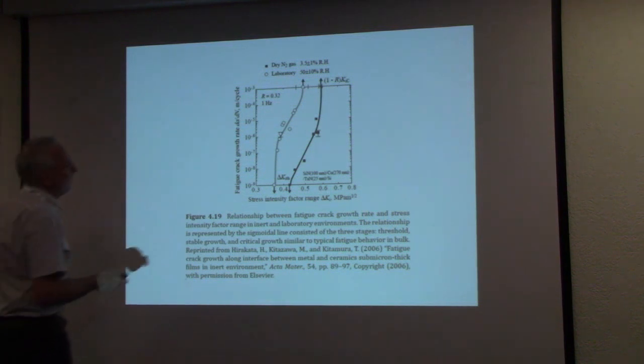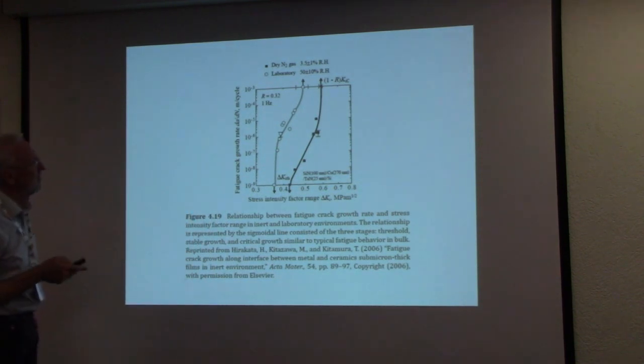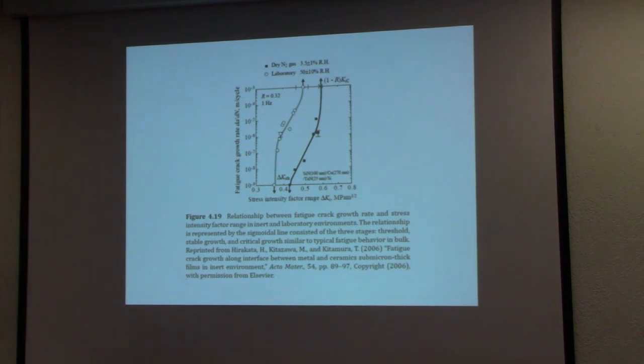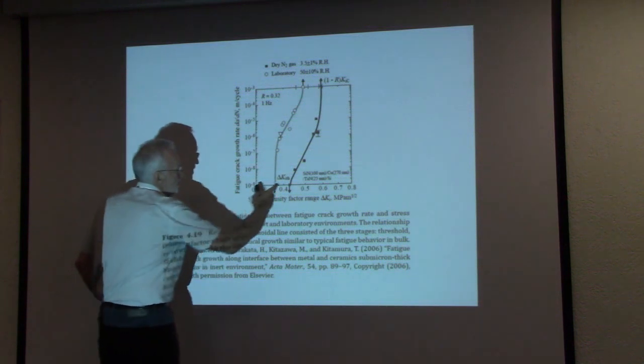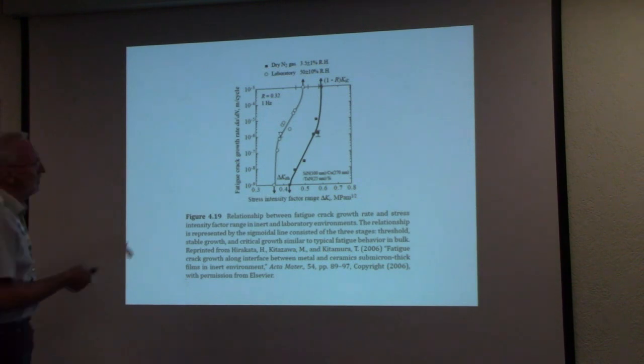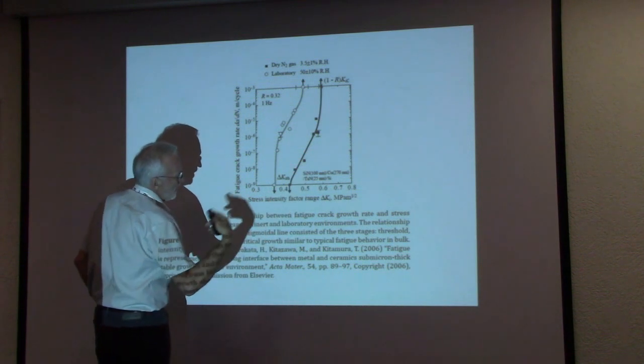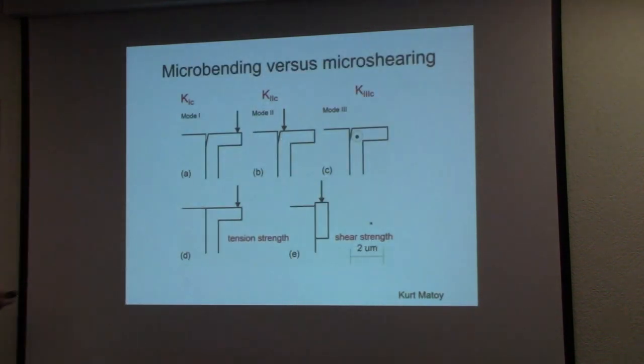In principle, you can draw such curves, as long as no significant plasticity in the metallic film takes place, then you can draw this line, or otherwise you have to determine this as a function of the film thickness. Or in this case, they are silicon nitride, so they are more or less semi-brittle phenomena.